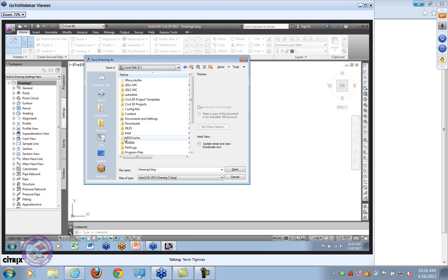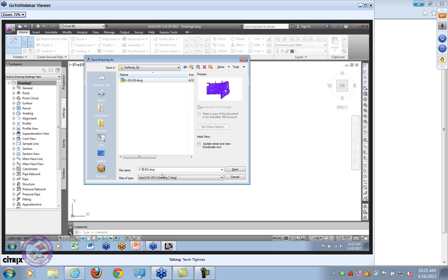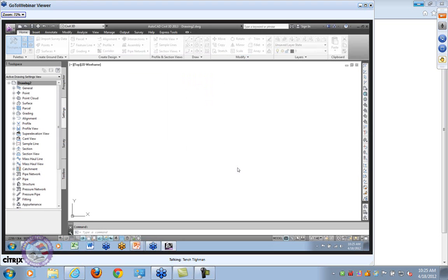No, not in My Documents. Let's save it inside my project, inside my 13. We're going to go down to existing conditions. We use an NCS-like model structure tweaked to work like Civil 3D. We're going to build the surface model in here. I've got a 10, so I'm just going to make an 11 here. We're making an existing one just to keep things simple. Things get a little more complicated when we're talking about proposed, obviously. And we're going to throw some data in here.